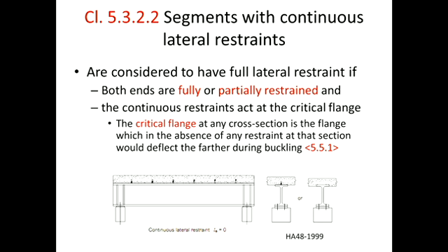So effectively this beam would be acting as a composite beam, but for this unit, we can analyze the beam just as a steel beam, but taking into account that the beam has continuous restraints. But maybe a little bit later, you can also look at this section and analyze it in terms of its bending strength as a composite section as well. But that's beyond the scope of this unit.